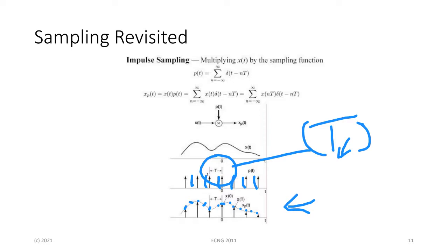As you can imagine, let's say I store a value, just a little larger here. So if the capacitor, for want of whatever the storage element, so let's say we're using a capacitor, has this value here, and this is our interval T. When we now start, we have the value here. Until we sample it again, the capacitor is going to hold this value. At the next interval, it charges up to whatever this particular value here is. So that's a new value, and it's going to hold that for T again.